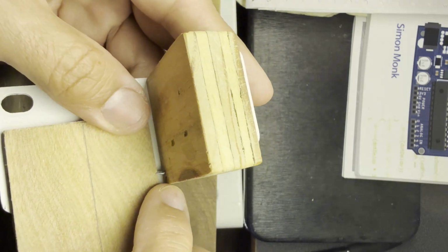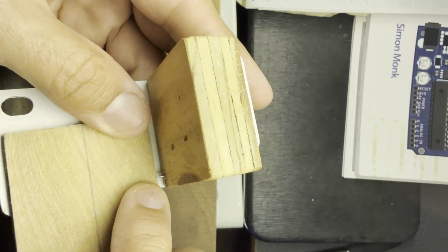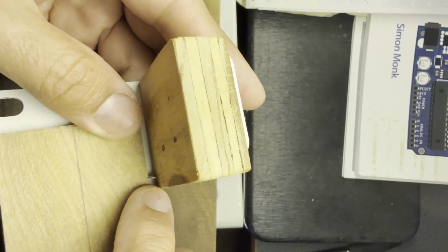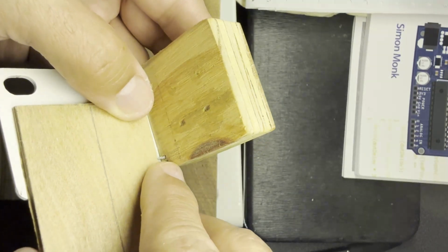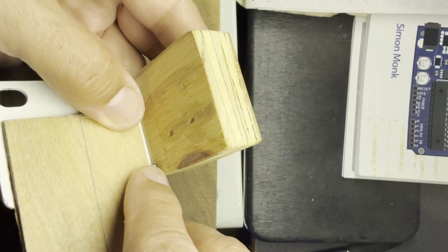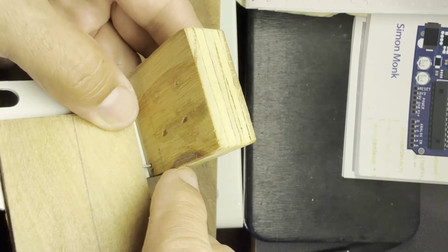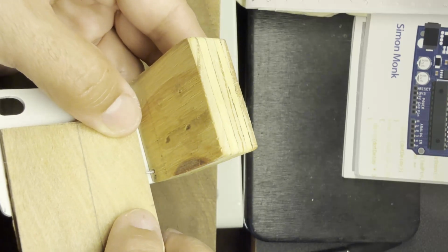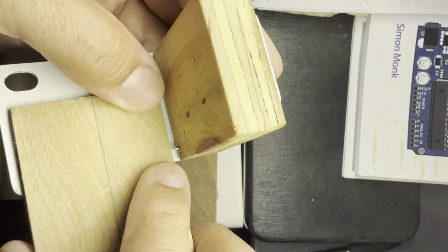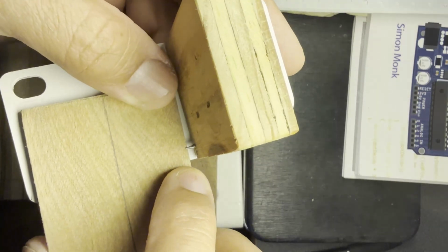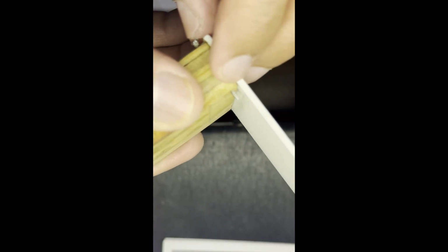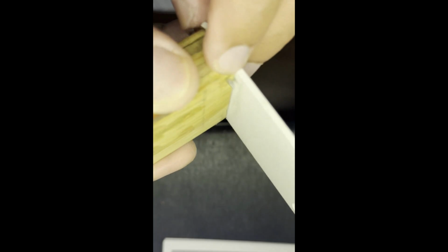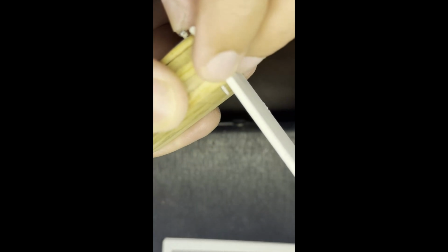Don't push it all the way down, otherwise that scribe is going to get skewed, because since I'm using a nail, the diameter of that tip is slightly different than the diameter that is sitting on the base of this piece of plywood. So you just let it touch the tip, and that would give you a fairly good approximation of the 2.5 millimeter gap. So the scribe I'm using, the nail, I shaped the tip using a machine file.